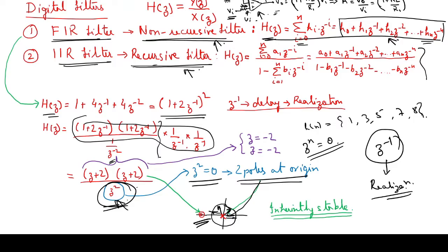So in a FIR filter, poles will not be able to help you in creating some filter responses. It will be very difficult, because for each of the frequencies the radius is 1. And we discussed in our last class that to modulate the frequency response, we need to place the pole nearer to the frequency axis so that we can create a specific frequency response. So that is now out of the question.